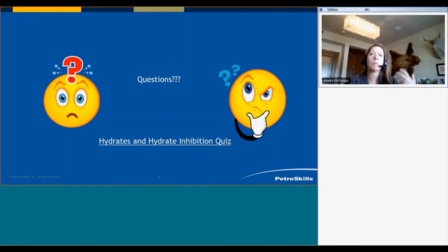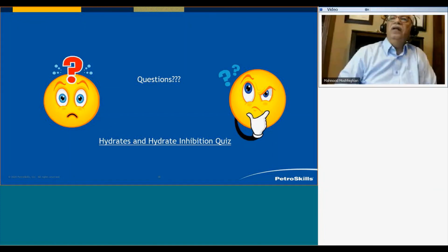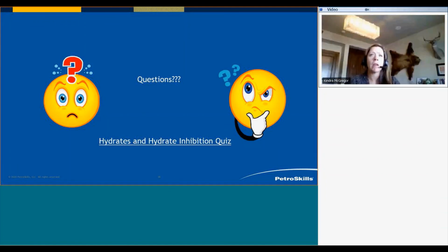Okay, there's another comment. If I'm going to dehydrate offshore, in that instance what type of glycol would you typically recommend, Mahmoud? Normally TEG as well, with dehydration if you use this. Excellent. Because the others are more expensive and much heavier compared to TEG. Yes, sir, absolutely.